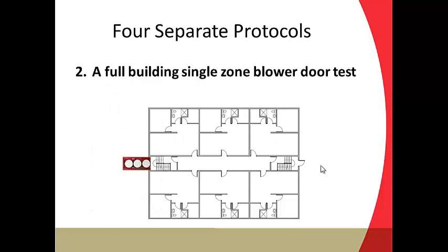Second option of the 4 protocols is doing a full building single zone blower door test. So that's pretty obvious and pretty straightforward. You just set it up in single family type conditions where you prop open all the interior doors and bring the whole building up to pressure.